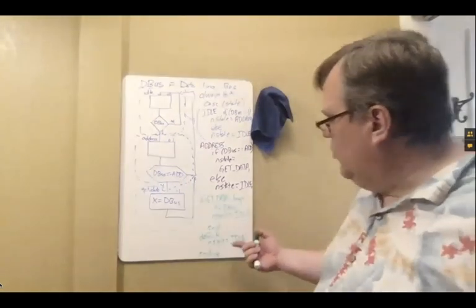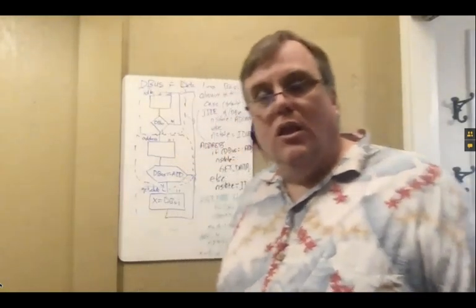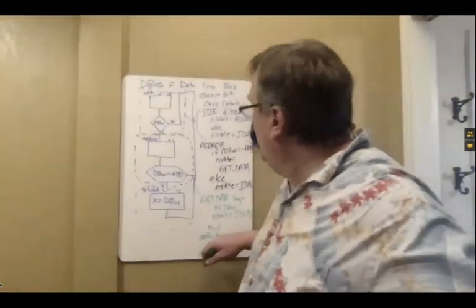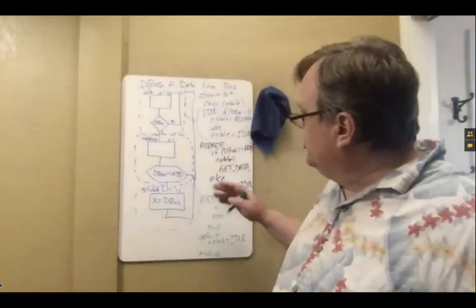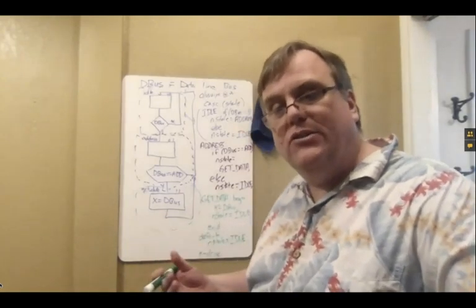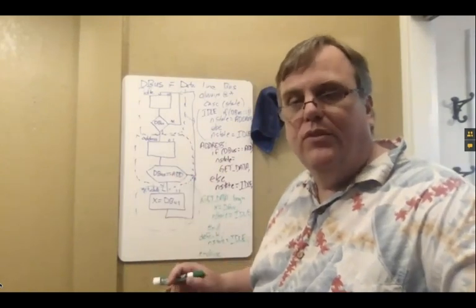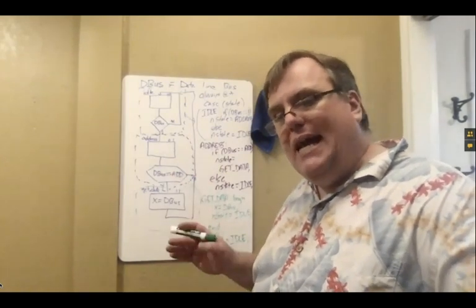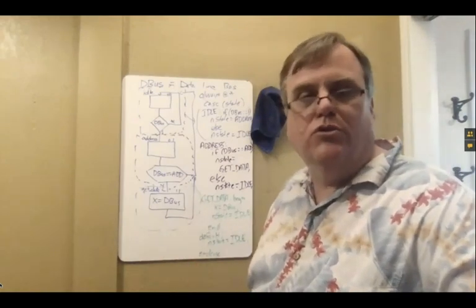One thing I might want to do is to go into an error handler. I could do a reset equals one. That is another good way to do it. The reset usually comes out, but I could send a request to the master saying, I've had an error. Can you send me a reset? Okay? And that actually allows the master to determine what it wants to do under those cases.